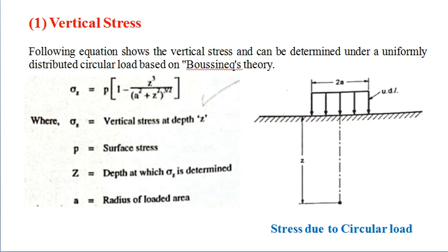and the assumptions made by Boussinesq were as follows. The soil mass is elastic, continuous, having a constant value of the modulus of elasticity E, and it obeys Hooke's law.